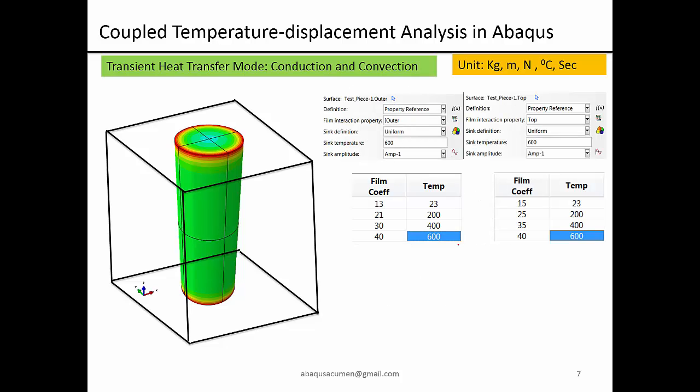What we are going to do is use this H, the convection heat transfer coefficient. This film coefficient will depend on the surface temperature. If your surface temperature is high, the heat transfer coefficient will be on the higher side. If you have a hot surface, air comes in contact with this surface and gets hot, its density becomes lighter, and it moves up. So you get a naturally high heat transfer coefficient with a higher temperature. That is what you actually see: the film coefficient is lower at room temperature, but as it moves higher, it becomes very high.